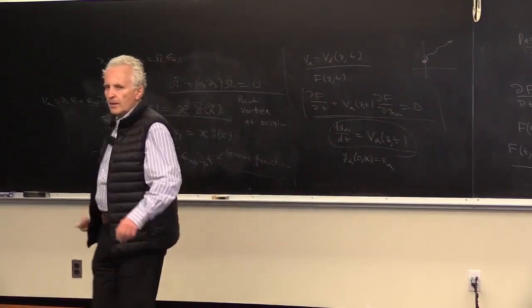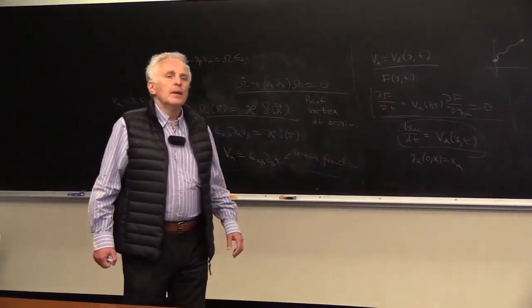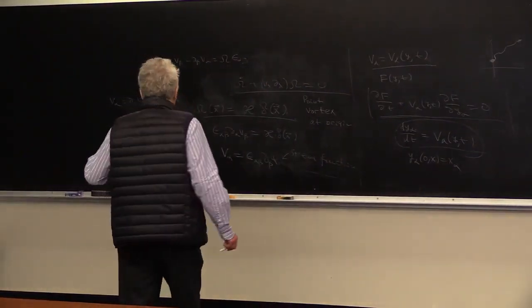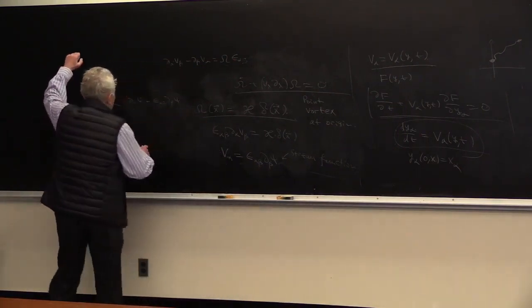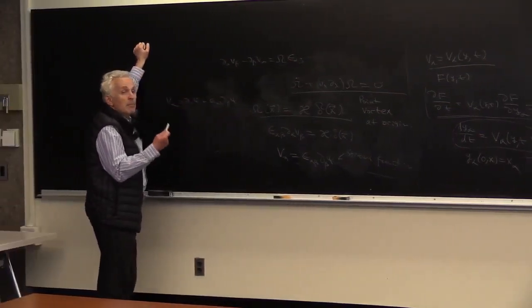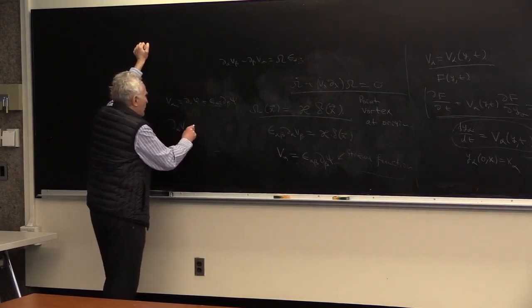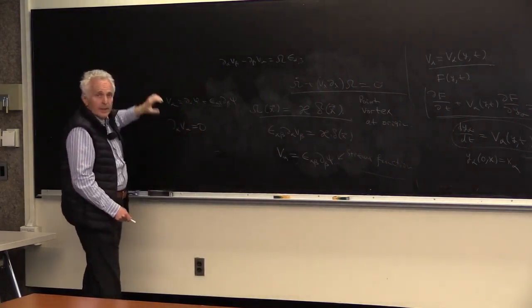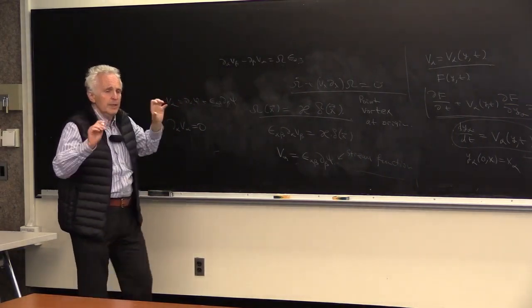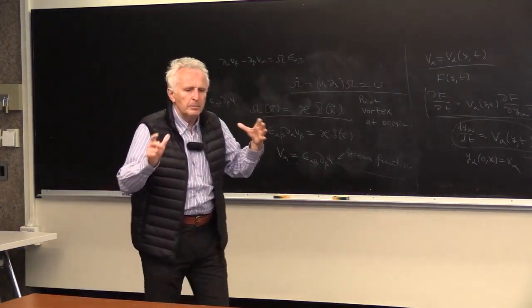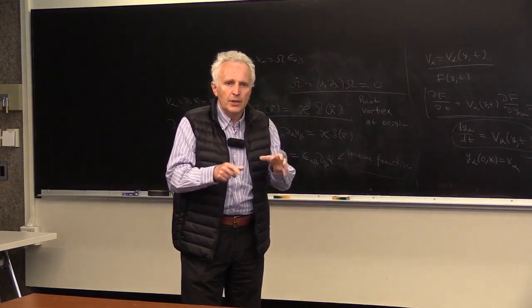Does it have to do with us only caring about the curl of V through the vortex? Actually, remember I said we assume that the fluid is incompressible. Incompressible means that the divergence of V is 0. That's the continuity equation. In general, if you set the density to be constant, it means the density doesn't change.